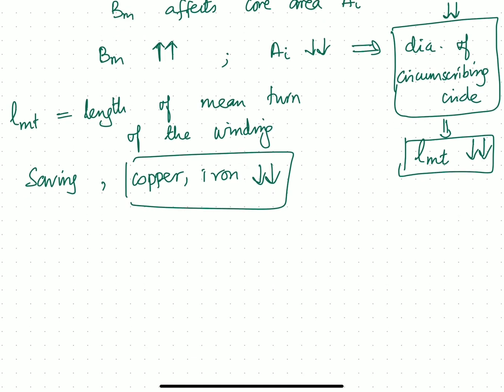However, you cannot simply go on increasing this flux density, because a higher flux density leads to an increased magnetizing current.